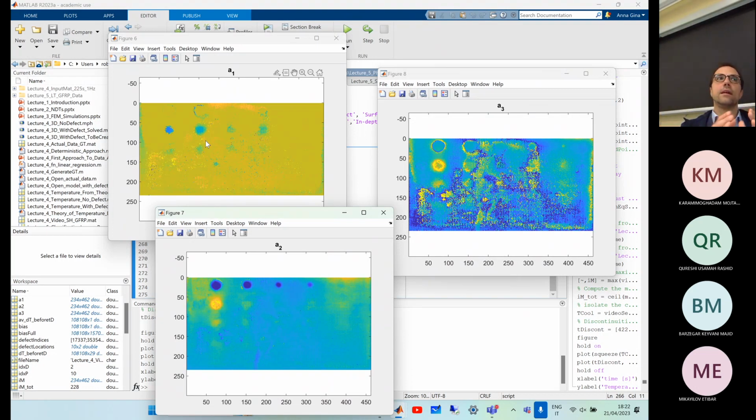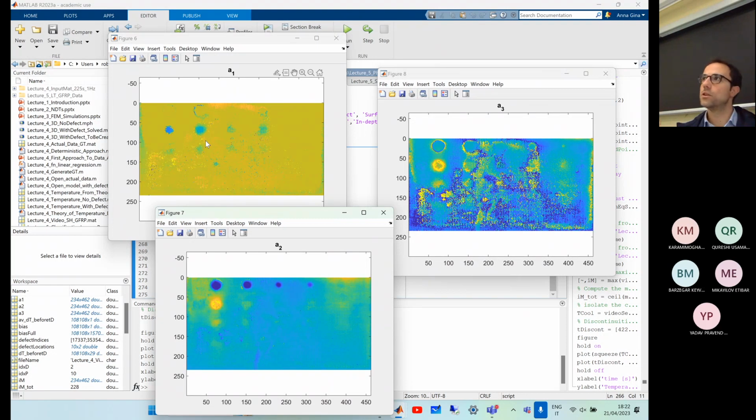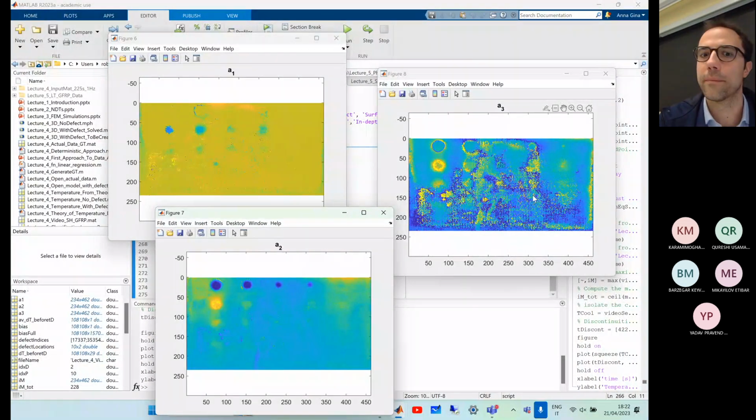So instead of having a whole video of 1,600 frames, I'm having 3 images. Okay, is almost the same of lock-in thermography. Instead of having the whole video lock-in thermography, I have just the amplitude and phase map that are, let's say, features for that problem. In my case, I got 3 features that are my best representation on my analytical problem.